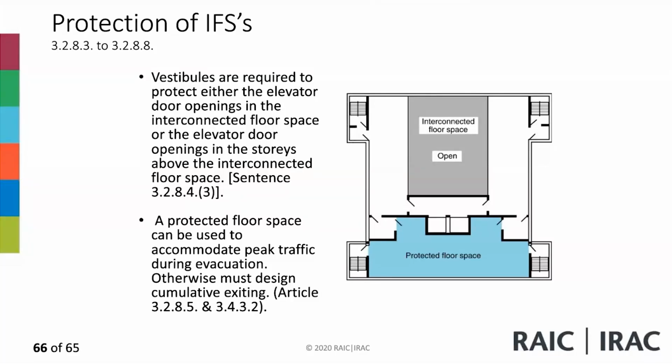3.4.3.2.6(b). The required exit for exit stairs that serve interconnected floor space shall be designed in accordance with Article 3.2.8.3, and the occupant load shall be cumulative. So for the stairs that serve the interconnected floor space, you basically add the number of people on all interconnected floor spaces to accommodate the exits and evaluate the exit capacity. Unless the stairs provide not less than 0.3 square meters of area of treads and landing for each occupant in the interconnected floor space.